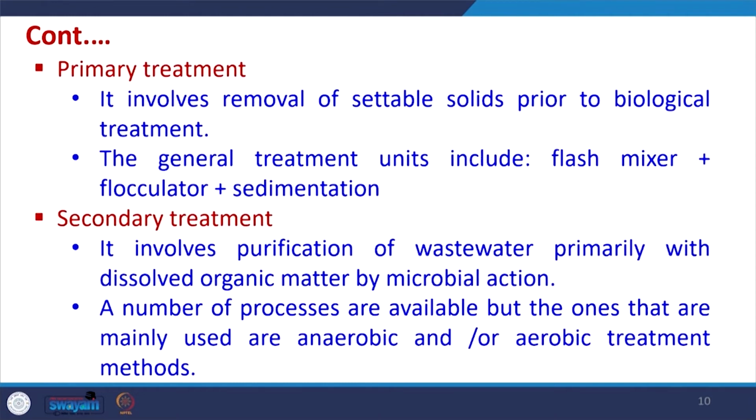Then primary treatment involves removal of settleable solids prior to biological treatment, and the general treatment units in this include flash mixer, flocculator, sedimentation basin. So, all these coagulation, flocculation things come into the primary treatment.